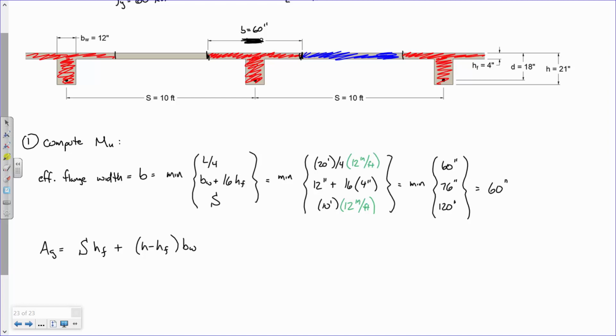I propose that. Okay? So what I've done is I took that B dimension and I replaced it with the girder spacing. Why did I replace it with the girder spacing? Because the girder spacing, halfway over and halfway over, that T-beam is responsible not just for its own self-weight, but the self-weight of that slab that's hanging out in space. Does that make sense?